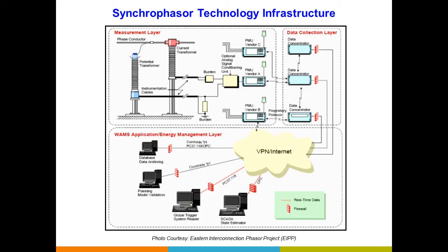Now these are sending the synchrophasor data through Ethernet to the different PDCs, or phasor data concentrators, which can be at the higher level substations or maybe the regional monitoring center, and then using again the Ethernet or VPN, we can send the data from these PDCs to higher level PDCs or the EMS applications, and the EMS applications can be of several types.